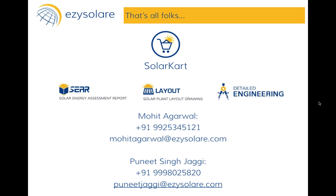But the key test which is done before commissioning to gauge performance and safety is that of performance ratio only, which is carried out for anywhere from 7 days to 30 days. Be mindful that this is just before commissioning. Typically, the EPC contractor is expected to have a skin in the game up till 1 year after commissioning.